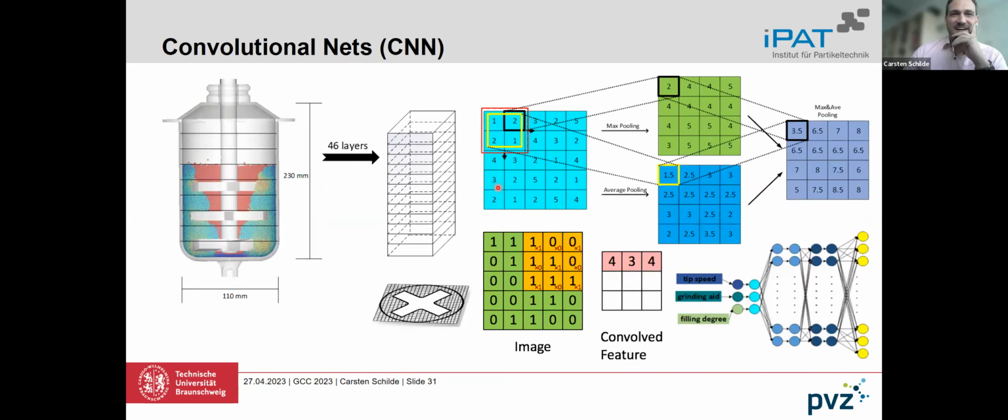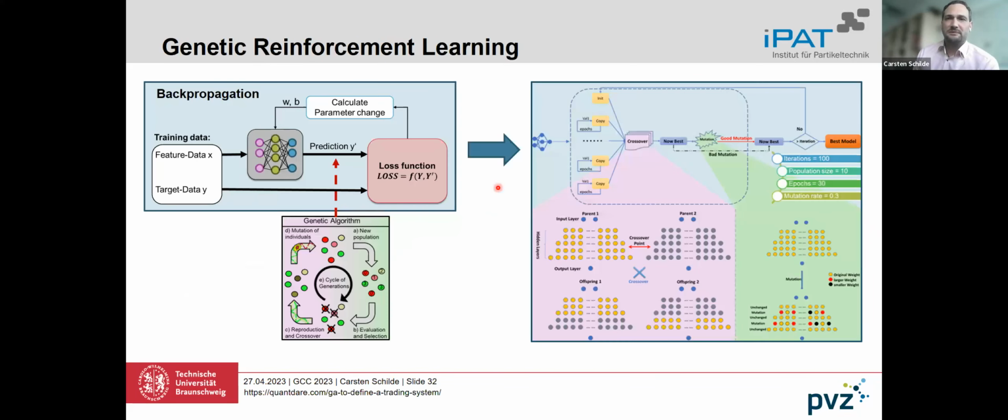And you can also go to dry grinding processes. Here we use a convolutional neural net to describe the whole stress energy distribution of the whole mill. We make some adaptations. We also put a genetic algorithm here in the machine learning after the simulation. So we simulate 15 simulations of the mill.